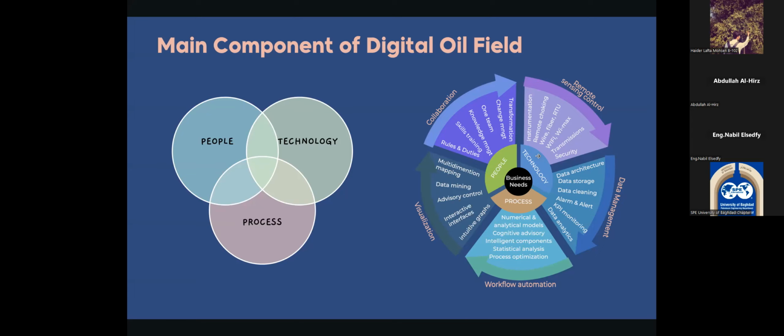There are a lot of rules, or a lot of ways, to fill that data. It's called imputation. You can build a machine learning model to fill that data, or maybe you can use the mean, or the average, of that data for specific events. You can set up algorithms, you can write code, or even the SCADA system may have that ability, so you can just drag and drop, telling the SCADA system that if you have missing data, you can use the mean or the average of that data to fill that gap.